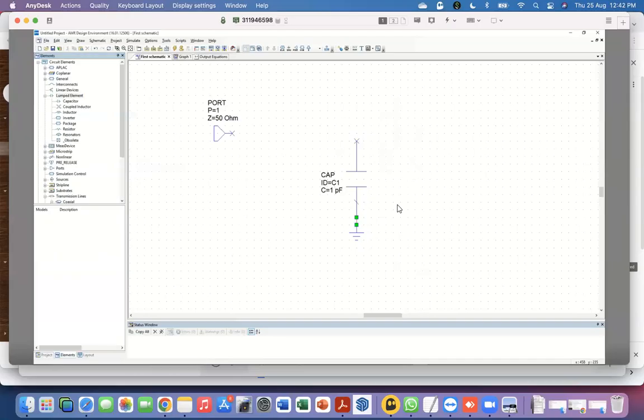Of course, in reality, in any situation, there is never a perfectly ideal lumped element. So all of these are approximations. But all the circuit analysis in electronics you have learned so far is under this lumped element approximation, that there is no difference in the phase of signals across different points of an extended circuit, because all of them are very small compared to the wavelength.